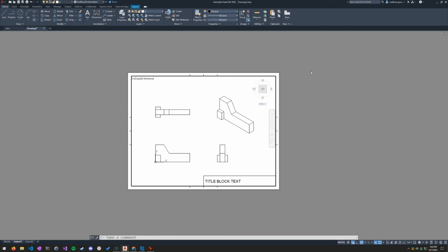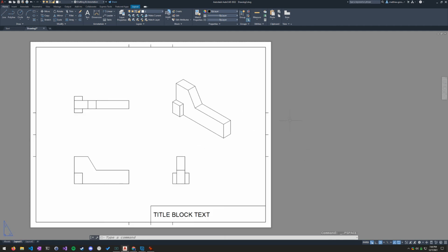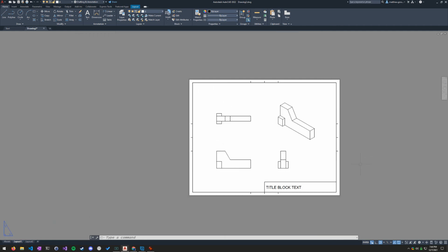All right. Either way, I still have the view cube. So remember, if I zoom in or out right now, it's going to change the way I've aligned things and completely ruin what I just did. So over here in this gray space, I'm going to double click to make the viewport go away. And see here, the command says that I'm in paper space now, which is what I want. And if I zoom, it doesn't mess things up. Perfect.